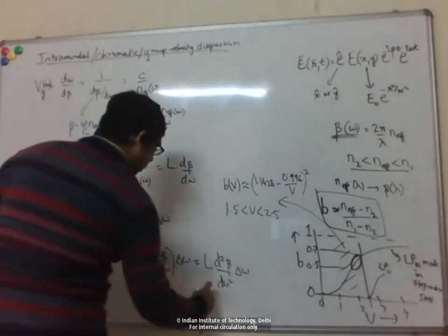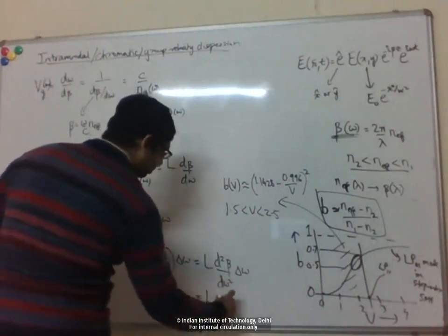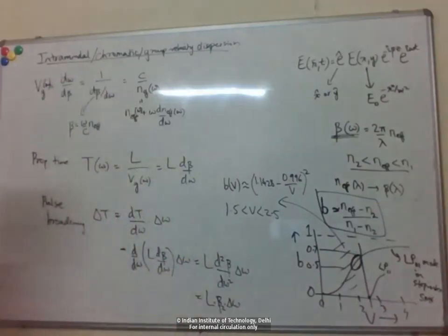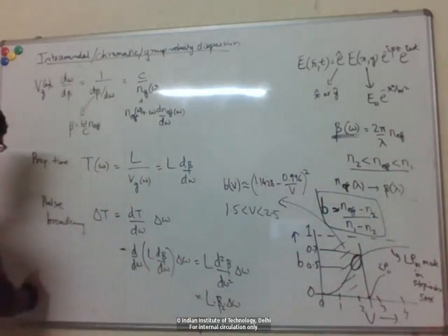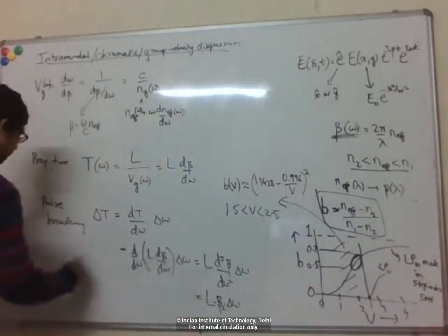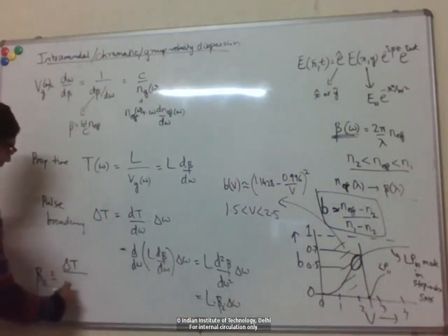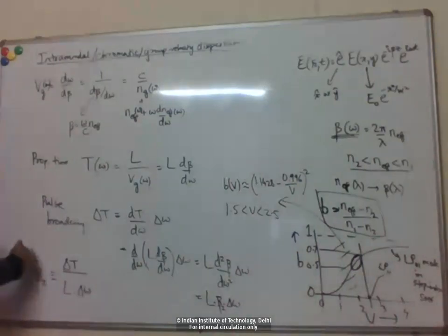Okay, so this is written as beta with a subscript 2 to denote the second derivative. So this beta 2 you can see is basically defined as the broadening per unit length per unit bandwidth. Right, so this is known as the GVD parameter or group velocity dispersion parameter.